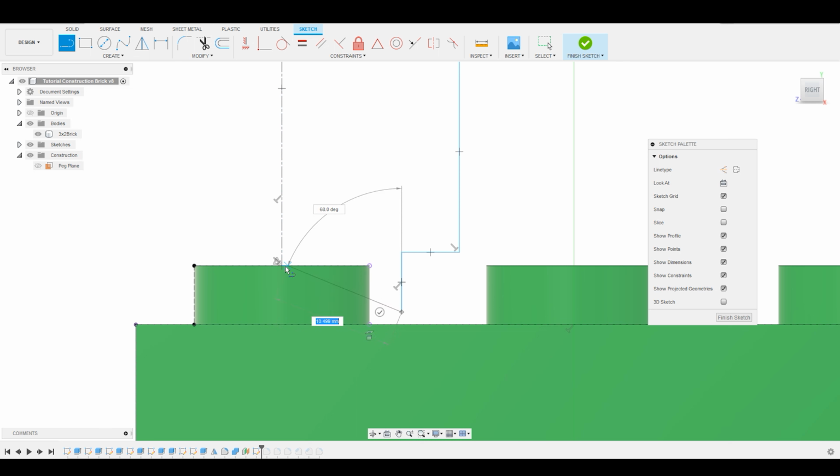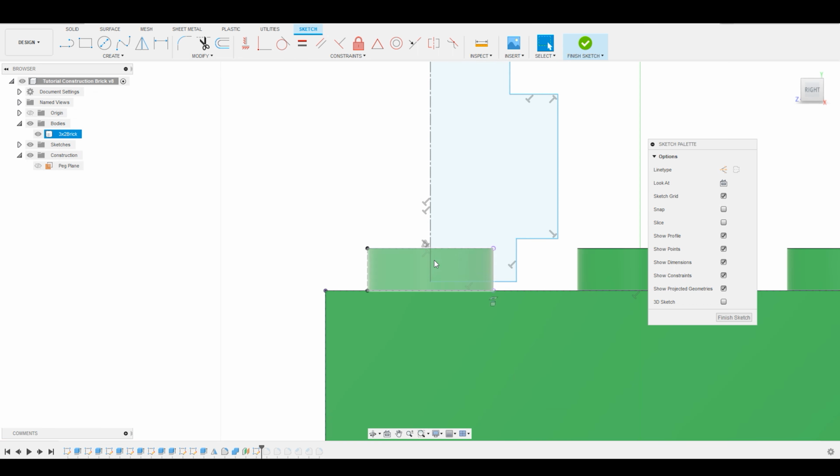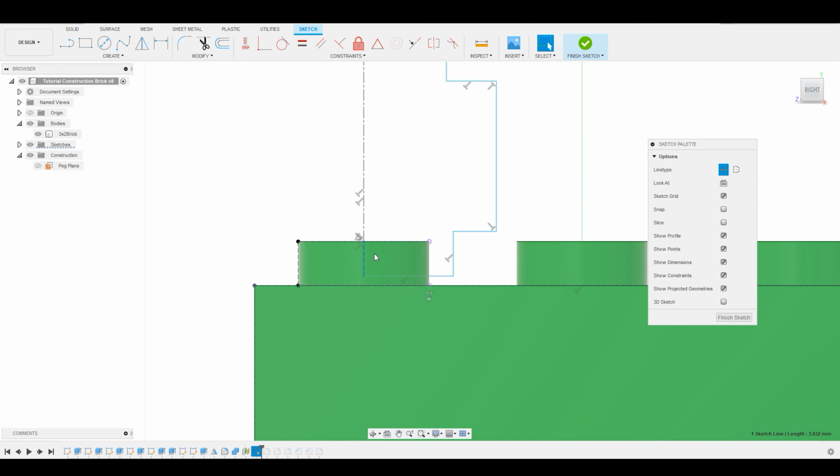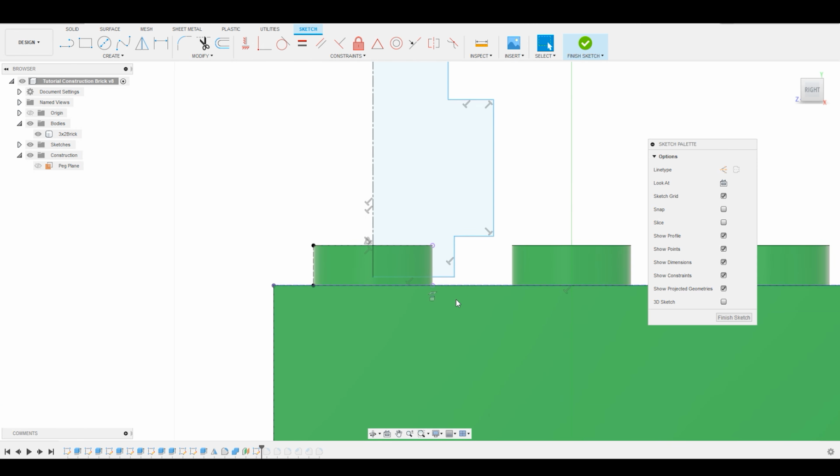And this is another great thing: if you have lines where you want them to connect, but they're not long enough, if you hover over it and then slowly drag down, it will still capture the tangent to that line. So I'll capture there, and then I'm going to close it up. Great. I can go ahead and turn this into construction geometry. Turn that back off. Never mind, because it turned not blue.